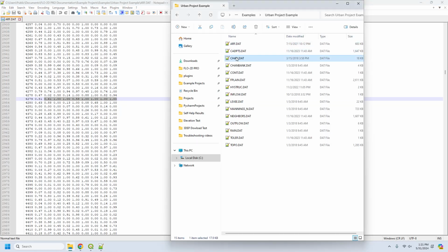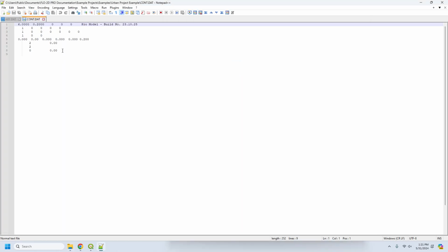The next one, let's skip channel. Cont.dat, what's not going to load in QGIS? I would suggest, if you don't have 7 numbers on this line, 1, 2, 3, 4, 5, 6, 7, QGIS won't load. Okay? Because that means it's a project that's older than 2009 or 2007, and you need tech support.